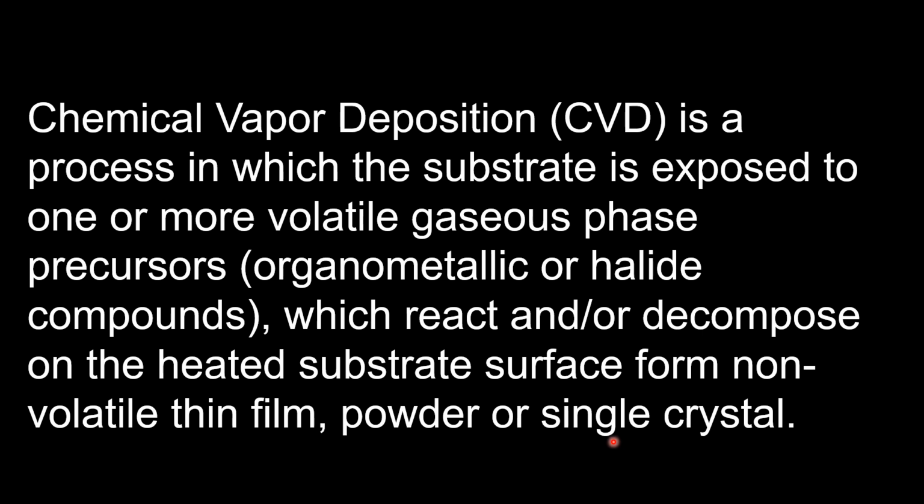So when the precursor material is introduced on the surface of this single crystal seed, if there is less lattice mismatch between the chemically prepared material and the seed, which is the substrate, then the deposited material formed after chemical deposition of the precursor will basically attain the same directional orientation as the seed or substrate material.